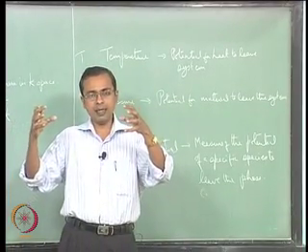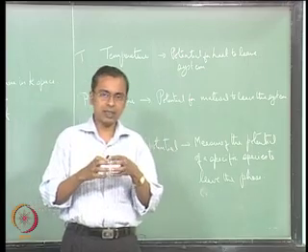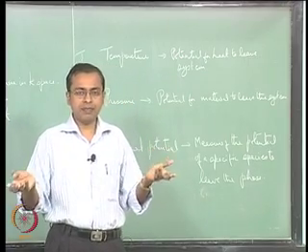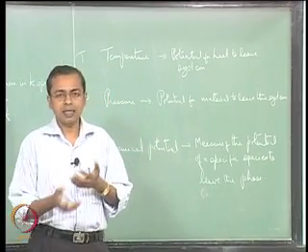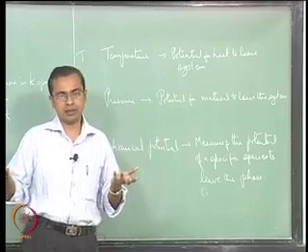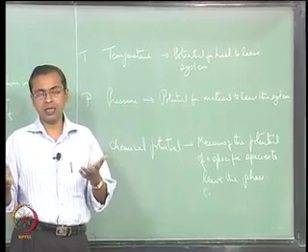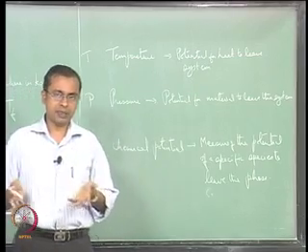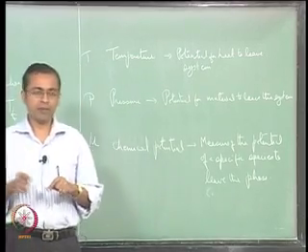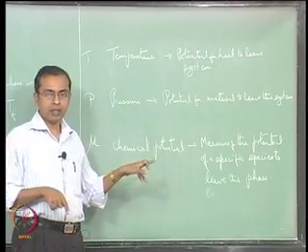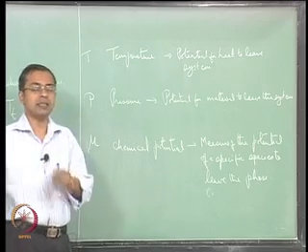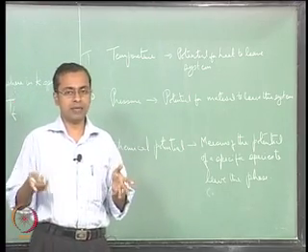When you typically bring these samples together, our conventional engineering experience is that carbon will diffuse from one sample to the other. As long as the percentages are not the same, it will diffuse. We normally simply talk in terms of percentages, but the more appropriate term there is in fact chemical potential. And they need not necessarily be the same, that is the important thing you have to remember.